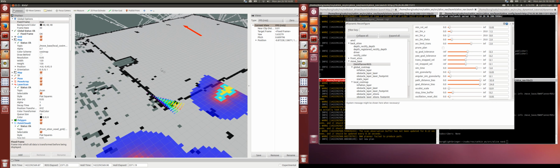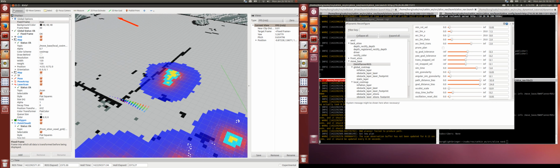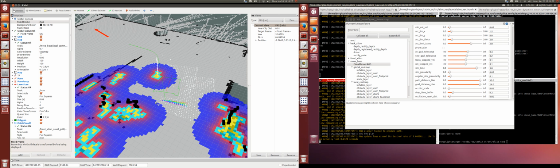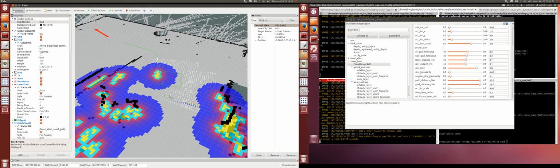First, I saw this debugging system where I can add a trajectory rollout planner and show it the possible trajectories that are being calculated, which is very informative and very good for debugging parameters. You need to actually download the source and enable it, because at least I didn't know other ways to do it. The only problem is it's not matching the robot movement, but it helps.